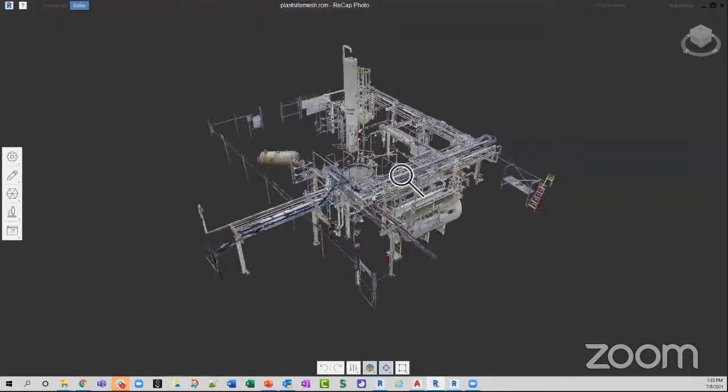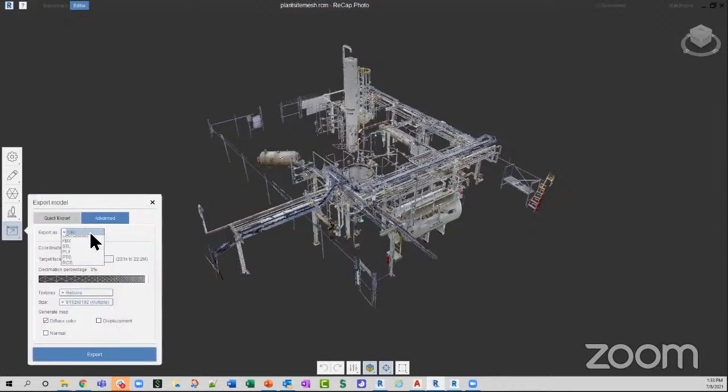Because you can see all of that 3D information. Whereas if you have a point cloud, it makes it a lot more difficult to tell which points are in front of which other points, and really getting that whole depth of view. Having that mesh file, that OBJ, the RCM, even if you wanted to export to FBX, just having that three-dimensional information makes it so much easier to visualize instead of trying to get a decent grasp on what these 14 million dots are actually representing.